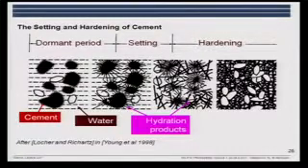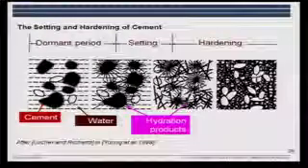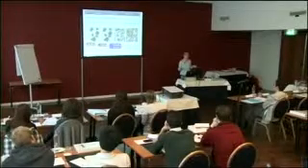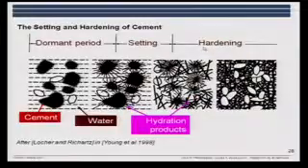The reaction will proceed, and at a certain time, the hydrates reach each other, and we have this stiffening, what we call the setting. The setting time is arbitrarily selected. It's just standardized. We have the initial setting, and we have the final setting. The information is used for how long you can actually work on your concrete and when you can start to do the finishing. So for planning of castings, it's important information. And then we have the increase in solids, and we have what we call the hardening period.